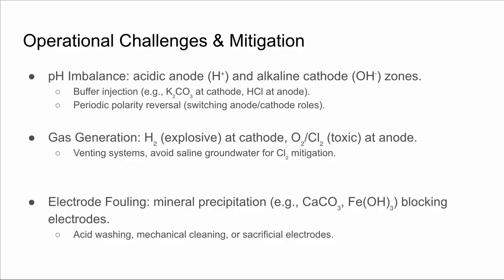Next, we can also face gas buildup during the process, which will be hydrogen, oxygen, and chlorine gas at the cathode and anode. That will require us to include venting systems in our process, and also avoiding salty groundwater would prevent chlorine gas from forming.